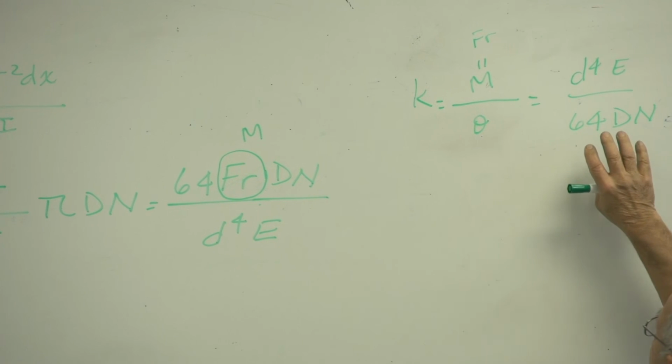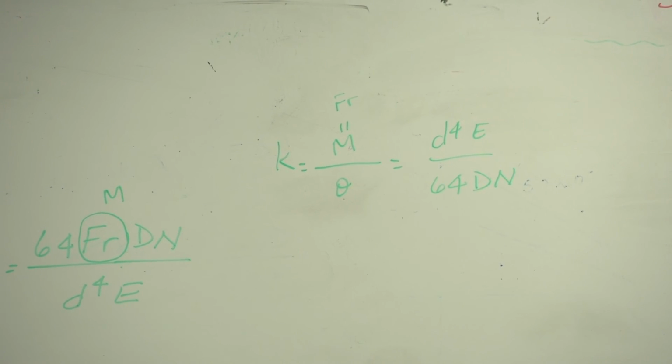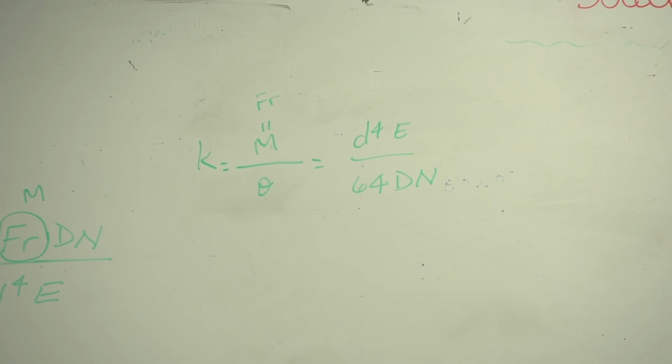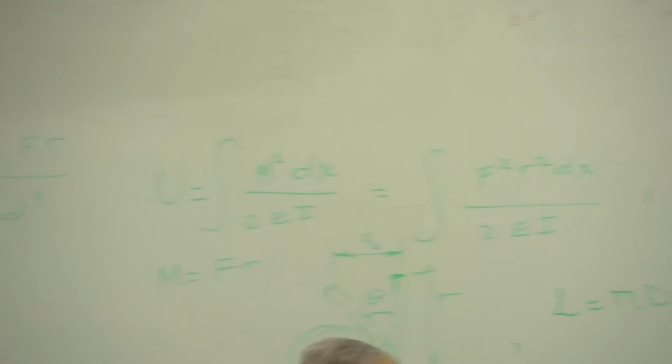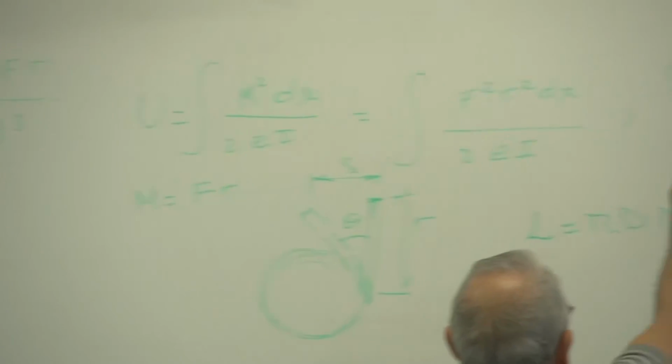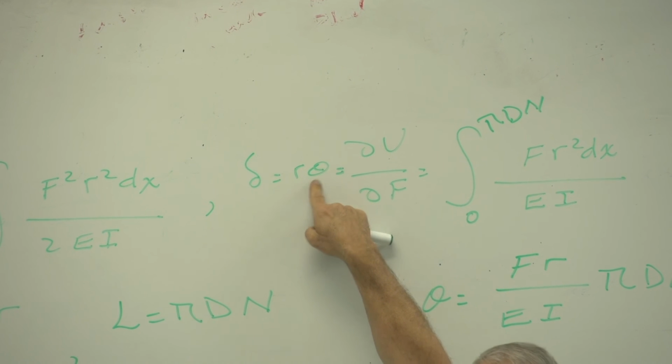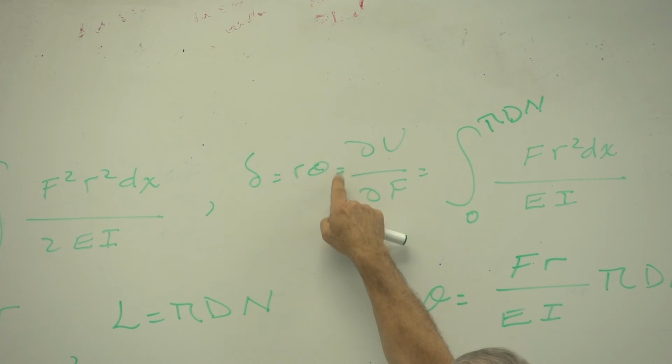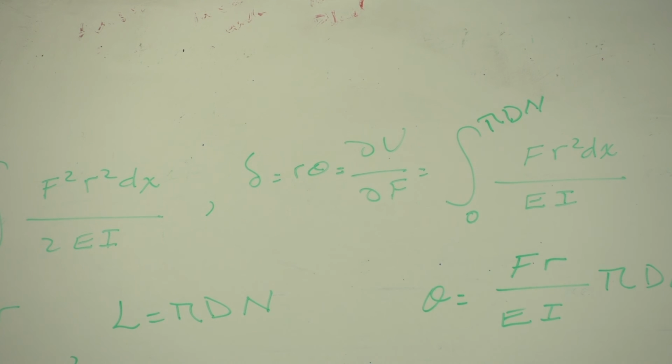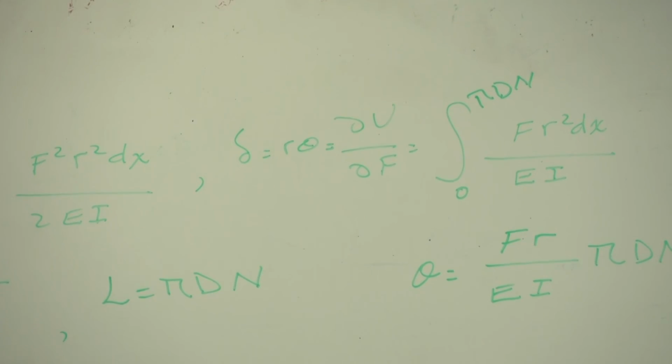What is the unit for this K? Moment per radian, that's right. So pound inch per radian. And usually per radian we don't say, it's pound inch, Newton meters, Newton millimeters, whatever. Because remember, this is in radians because I wrote that equation. That's only true if theta is in radians. It's not true if it's in rotations or degrees or anything like that.